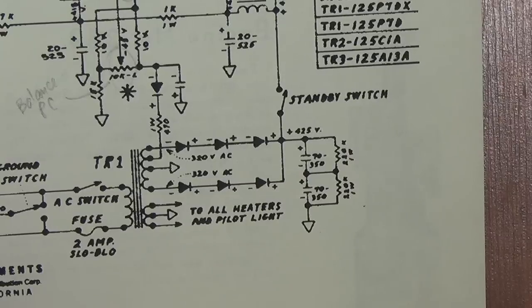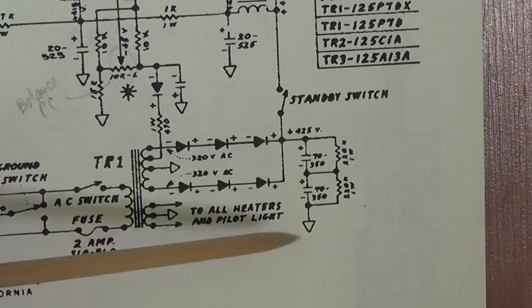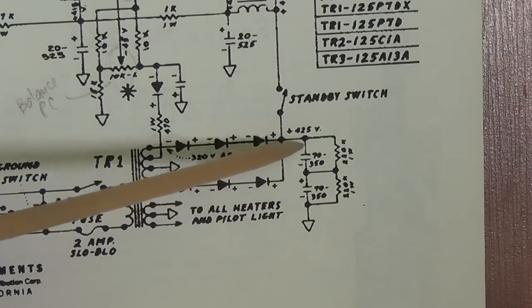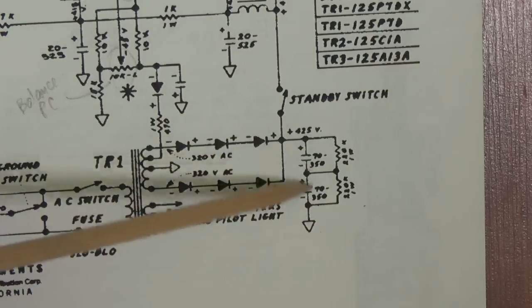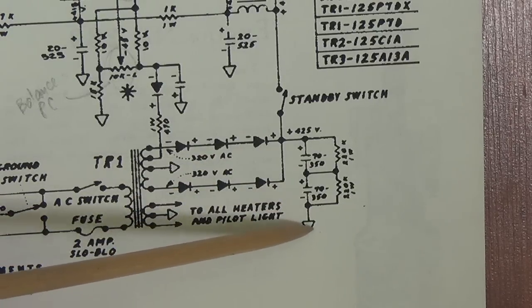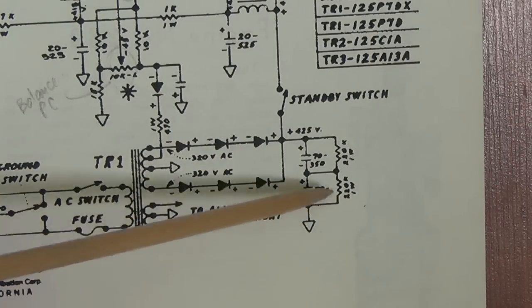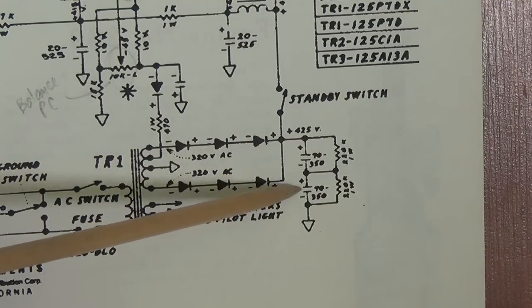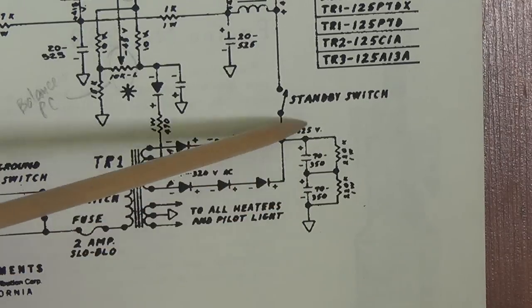Now, you know as well as I do, you can't find 700 volt capacitors very easily. So for just a few dollars, and by wiring a pair of very common electrolytic capacitors in series, here we will achieve the 35 microfarad capacitance that we seek at a whopping 700 working volts.